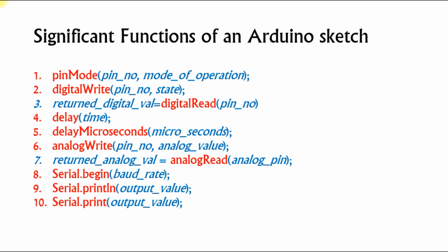Then delayMicroseconds. There is a dedicated command available in the Arduino IDE for producing microsecond time intervals. If you give 1000 within the bracket of delayMicroseconds, it will execute a delay of 1000 microseconds, that's all, right? So these are the delay commands.